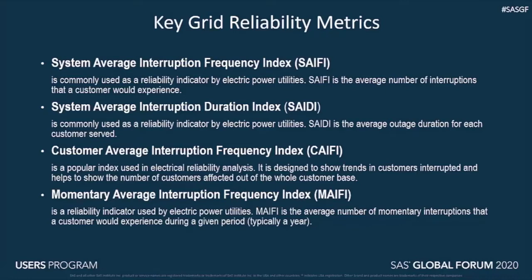The most often used performance measurement for a sustained interruption in the system is the System Average Interruption Duration Index. This index measures the total duration of an interruption for an average customer during a given period. It is normally calculated on either a monthly or yearly basis. However, it can be calculated daily.